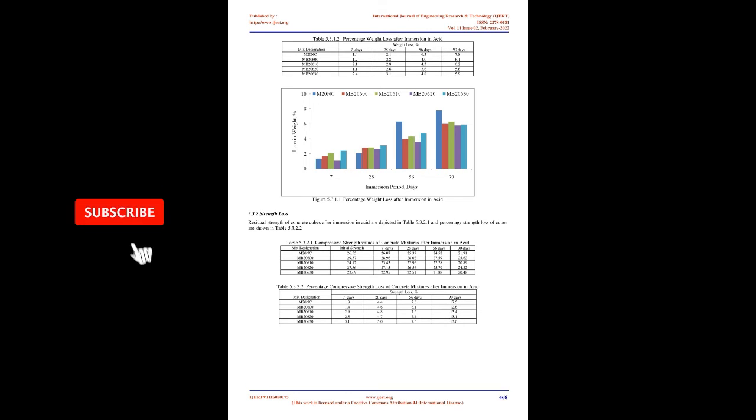4.2 Split Tensile Strength Test. A diametric compressive load will be applied along the length of a 150 x 300 mm concrete cylinder at a continuous rate until failure occurs. This loading induces tensile stresses on the plane containing the applied load, causing tensile failure of the sample. IS 5816:1999 formed the basis for the development of this procedure.